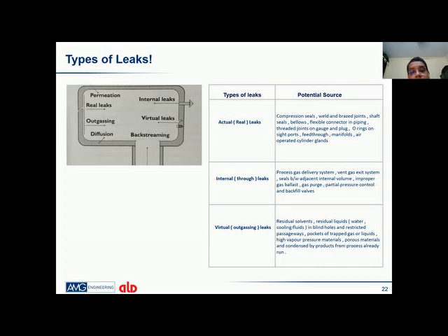So what is happening is that all these gases and leaks, because things move from high pressure to low pressure, are trying to reduce this vacuum level from -5 to -4 or -3. But we have to see which leaks will be hampering our parts, where the part quality will be more critical.